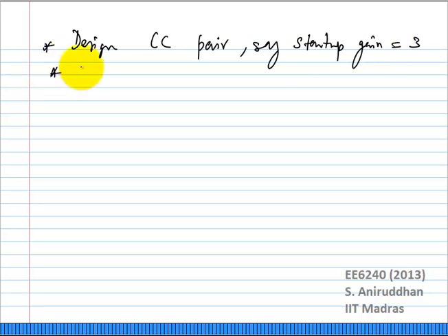What next? GM is fixed. Now, no, IT is already fixed earlier. We are going to use the maximum current possible, right? And based on that, you are going to choose the width such that GM has a certain value. What next? Now you need to ensure tuning range. You have ensured maximum amplitude for phase noise. You have ensured maximum current consumption possible. Next step is to design for the tuning range.